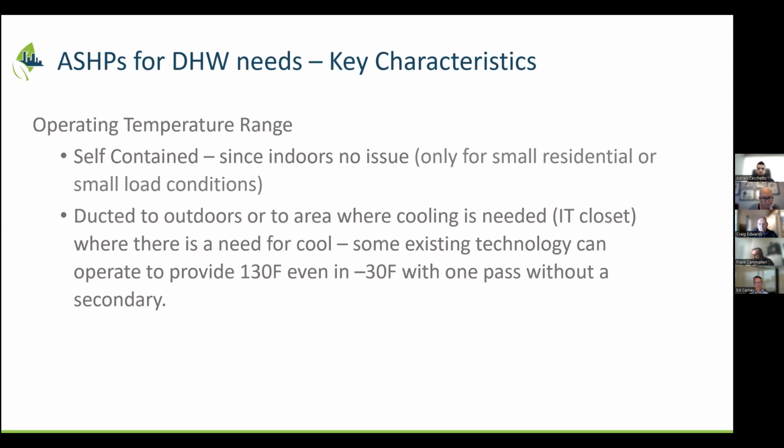Just continuing on that, the operating ranges, which I just mentioned over here, that they can operate even in minus 30 degrees Fahrenheit. What are you seeing out there in terms of technology? Even though it can go down to minus 30, are you seeing the air source domestic hot water heat pumps being packaged with backup heat? And if so, what types are you usually seeing as that backup? So with the nature of the refrigerant-based air source heat pumps, what happens, anybody's system, is the colder the temperature outside, the performance slowly drops off.